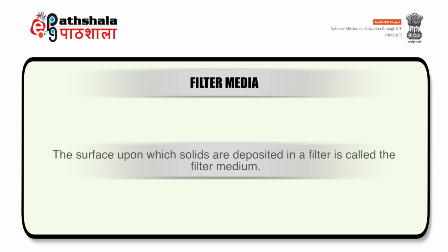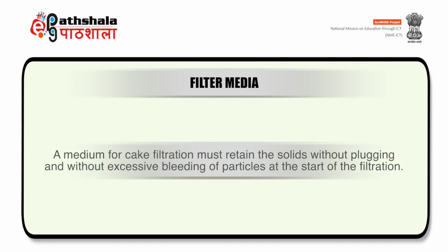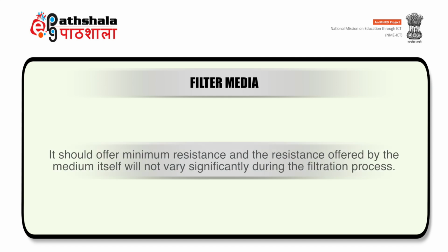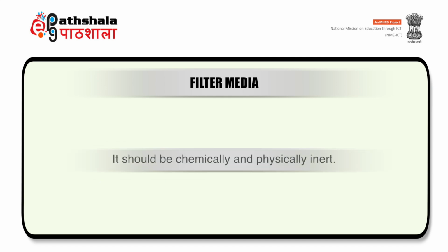Filter media is the surface upon which solids are deposited in a filter. Now some of the characteristics of filter media are: first, they must retain solids without plugging and without excessive bleeding of particles. Second, they should offer minimum resistance. Third, filter media should be chemically and physically inert.